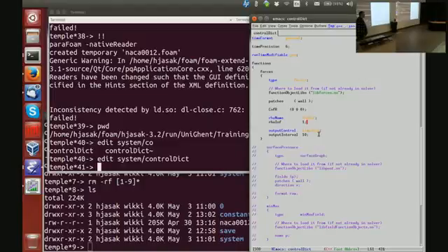You remember what I told you about the density? The incompressible solvers are divided through by the density, but for the force I want the density. So here I can specify rho infinity of 1 to allow me to calculate the force out of the kinematic pressure.